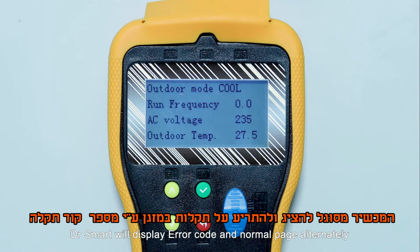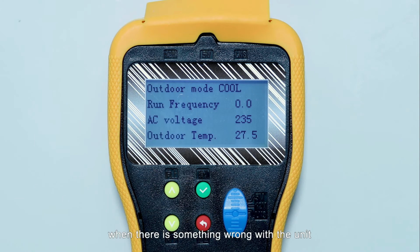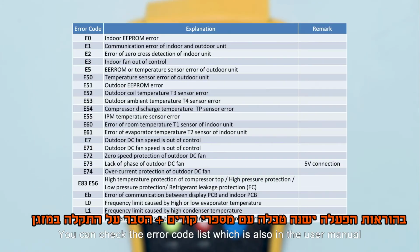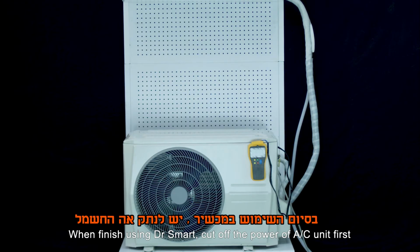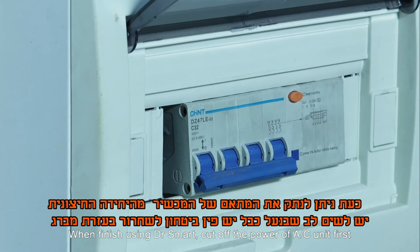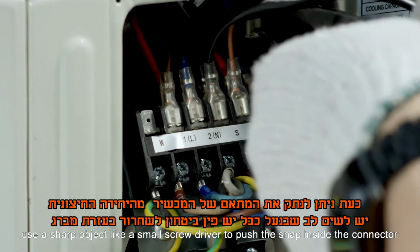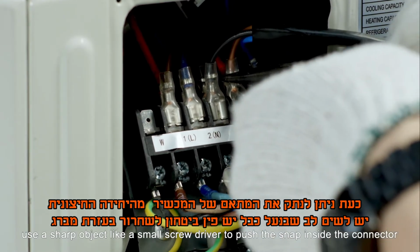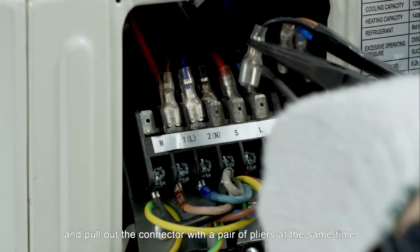Dr. Smart will display error code and normal page alternately when there is something wrong with the unit. You can check the error code list, which is also in the user manual. When finished using Dr. Smart, cut off the power to air conditioner unit first. When disconnected, use a sharp object like a small screwdriver to push the snap inside the connector and pull out the connector with a pair of pliers at the same time.